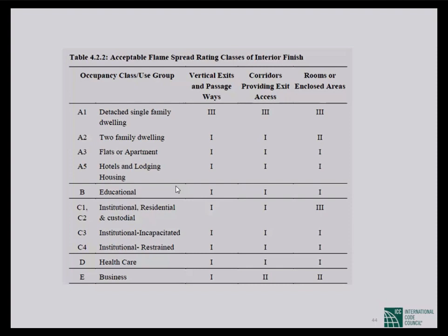There you can use different types of material. So one thing you have to remember: type 3 is very easily combustible. Type 1 is non-combustible. That means if you choose a type 1 material, the flame is not moving very fast. It is the lowest type of flame movement, and it is heat resistant. But if it is type 3, it is not heat resistant. It is a fast moving material where fire can move very easily. If it is 3, fire can move very easily. If it is 1, fire cannot move very easily. Fire, that means flame or fire, whatever you say.